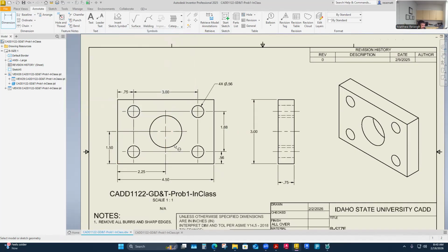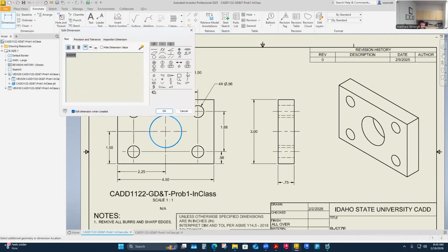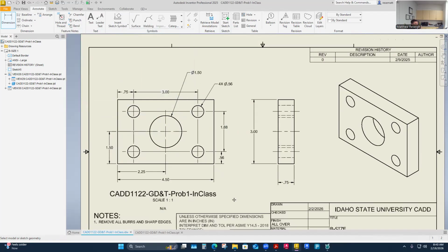And I just haven't sized that, but I've located it, so I should have sized it first. But yes, size of that hole, let's put it like we would in a normal drawing. There it is, 1.5 inches. Go ahead and drop that. There's only one of those. So really, with a little cleanup here, I would dang near be done on our normal drafting, right? And we would think like, yep, go ahead and make this good. So now we got to make this way overcomplicated. But in some ways, it's less color.